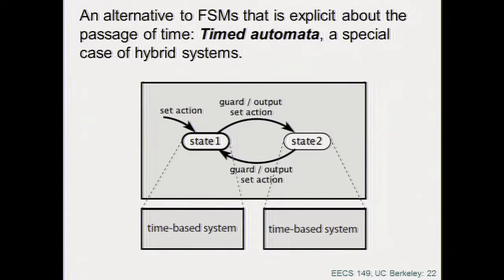And then you have to take out the loads, right? And what do you need to do to take out the loads? You open other contactors, right? So you close this, you open that. So that is a hybrid system, right? This is discrete: there is a number of states, this is down, this is up, combination 2 to the n of these switches up and down, and this is the number of states. And you switch from one state to the next if something happens, right? Okay, so that's it. So this particular modeling strategy is very, very effective.